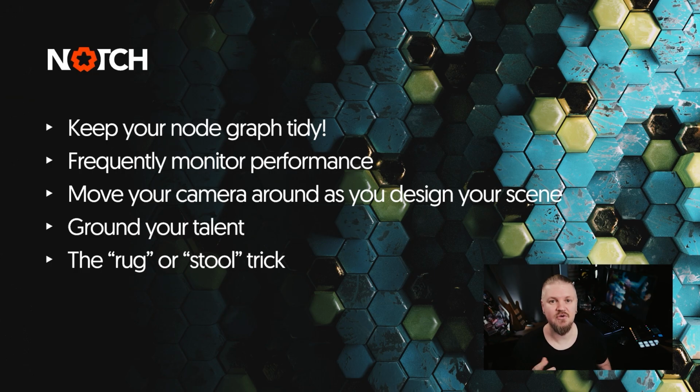Alright, that's a lot about optimization, but I talk a lot about it because it is important. So let's wrap up the optimization section of this course with some additional quick tips. Let's start with keeping your node graph tidy. Clean it up as you go and remove nodes you no longer use. It is important to frequently monitor performance and make sure that the project runs fine at or above the final resolution and FPS requirements. Remember that overscan increases the rendering resolution.